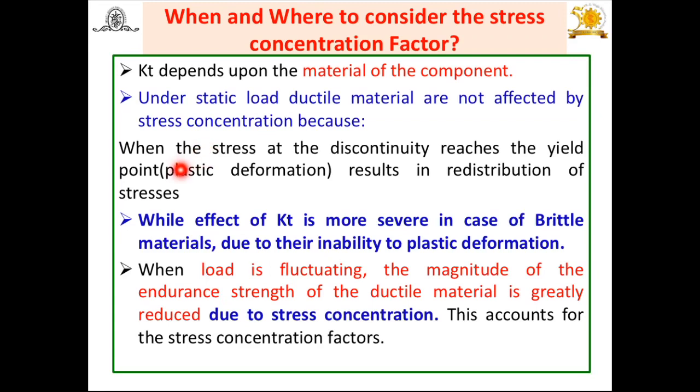Why? Because when the stress concentration at the discontinuity reaches the yield point, imagine your stress-strain curve, you will find when it reaches the yield point, that time plastic deformation starts, and when plastic deformation starts, it results in redistribution of the stresses, and because of that, no need to consider the stress concentration in case of ductile material subjected to static load condition. Try to understand. That means under static load, when ductile material is used, no need to consider stress concentration factor.